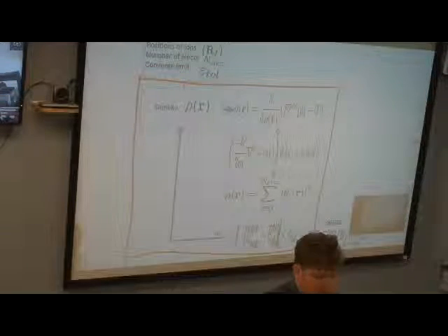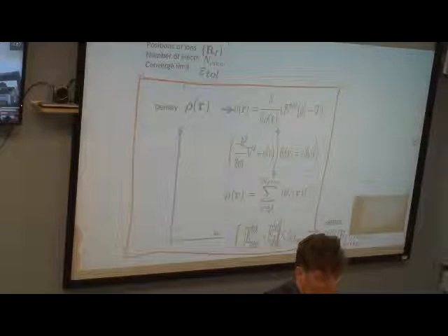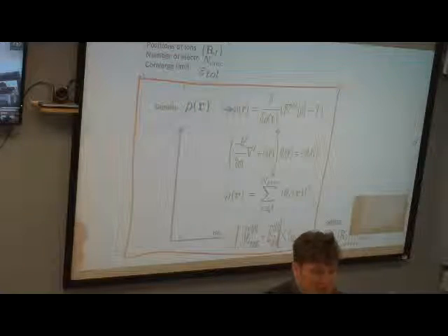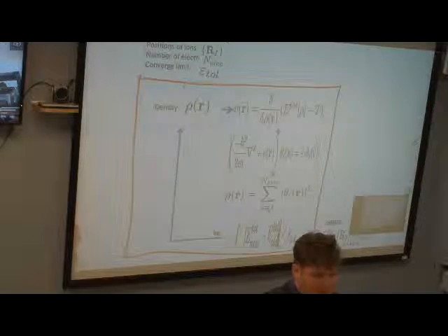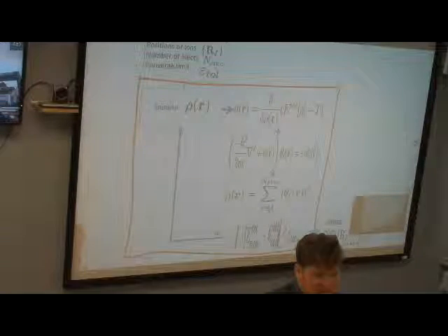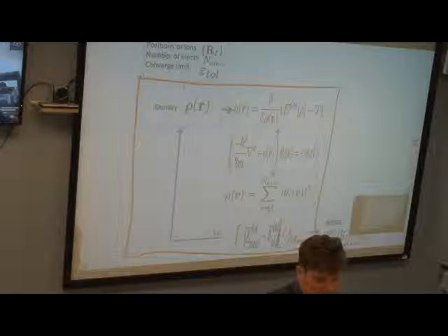Okay, because you are so educated and smart. When I was learning the software, I tried it several times. So it is an error. If there is no WAVECAR, there is no reason to find orbitals. But if you try to do it, it will be garbage. You see little clouds at each side of the simulation cell, which shows how VASP generates random density with a random number generator.